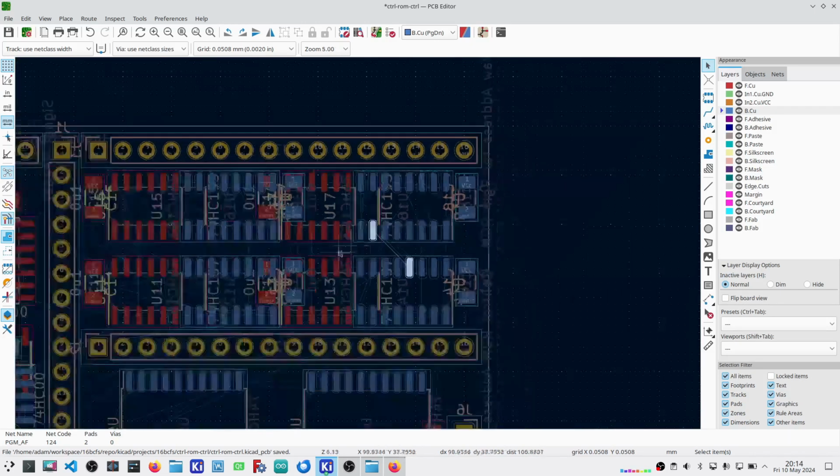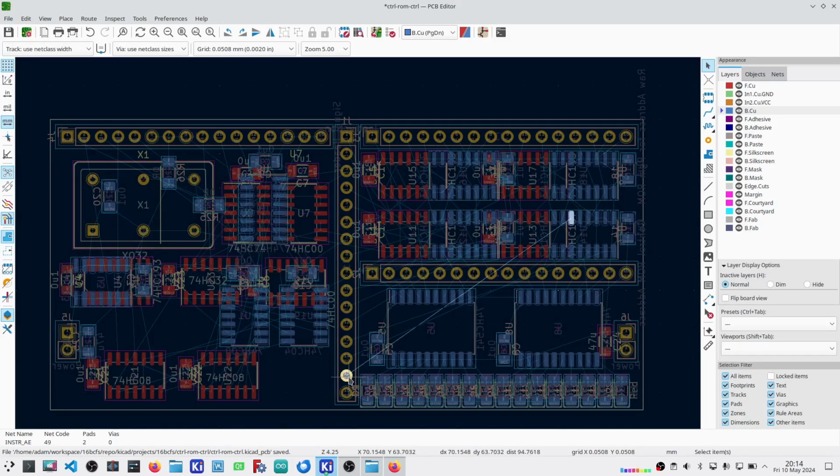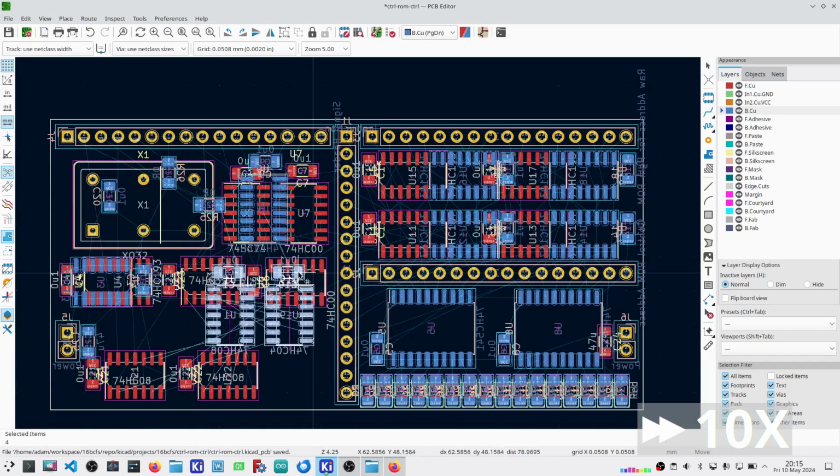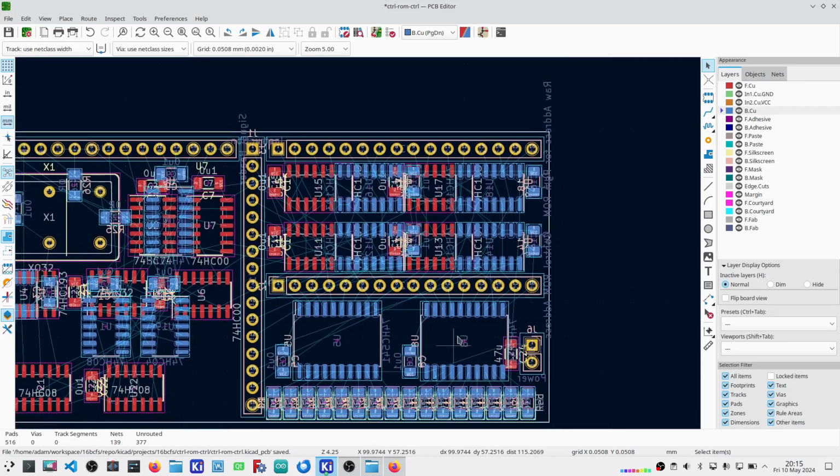The other side of this is there are signals from here, and they'll be down here. That needs to make its way up over here. This needs to make its way up over here. Now I've got a lot of space in between the rows of pins here for the line drivers that I could take advantage of. So I do believe I'll be pulling a lot of signals down this direction and then over along this way. We'll have to see how that all works out. I may have to make some room over here for some of that stuff. As a matter of fact, let me do that now. That should give me room on this side, on the back side, to bring those signals down and then over.